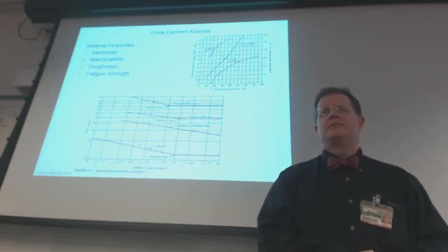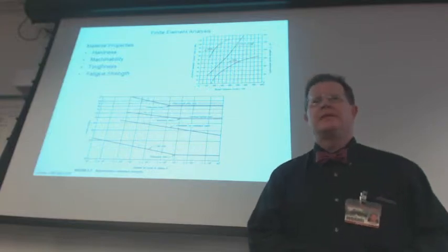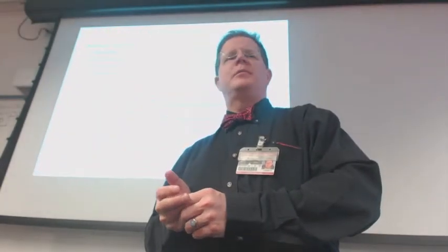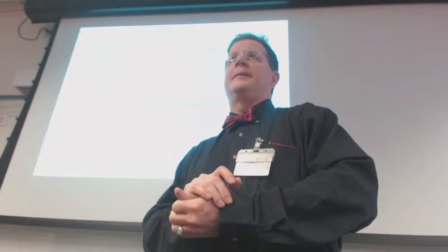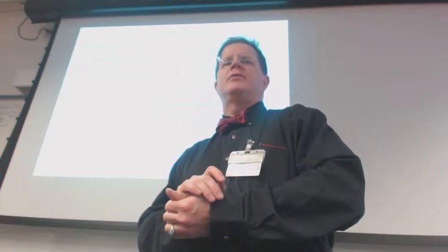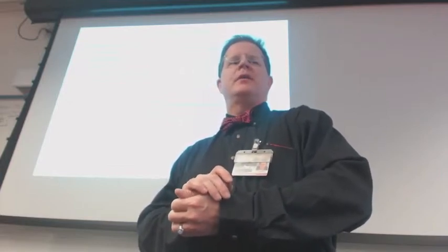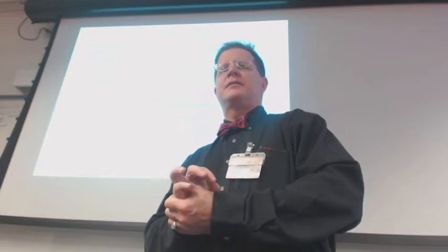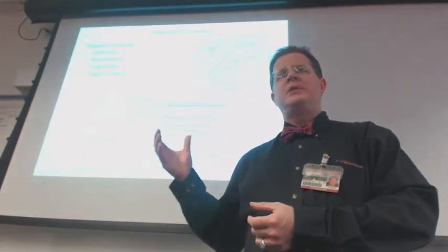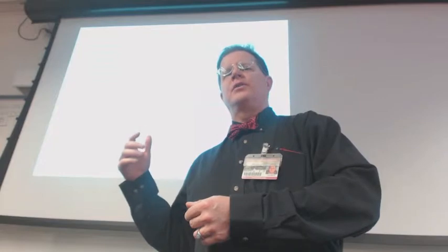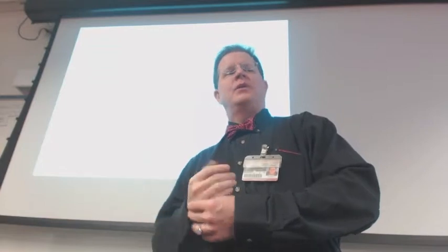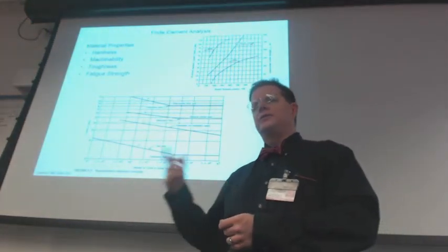That one's easy. Just what it says, right? How well it machines. Because some materials are pretty easy to machine and some are just a real bear, depending on their properties. You can get steel that has lead in it, so that makes it really easy to machine or turn. If you're dealing with stainless, you have to be careful with your feeds and speeds, because you can work harden the material if you're going too fast or even going too slowly. So there's kind of a sweet spot that you want to be in. Otherwise, you just start breaking tooling.